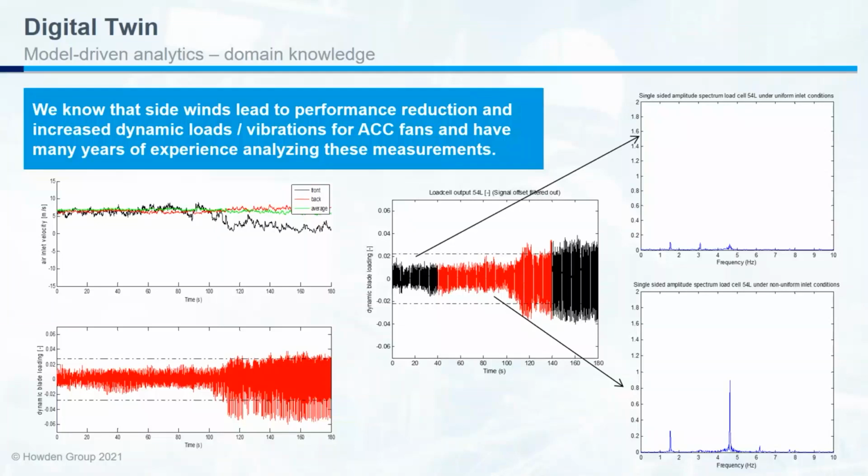We are aiming to do a fast Fourier transform, which will be a big benefit to locate the failure modes connected to what you're seeing. We would typically expect to see certain harmonics under stable operations, and others as a result of resonance occurring due to increased dynamic loads.